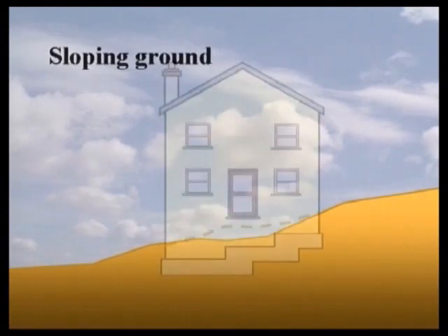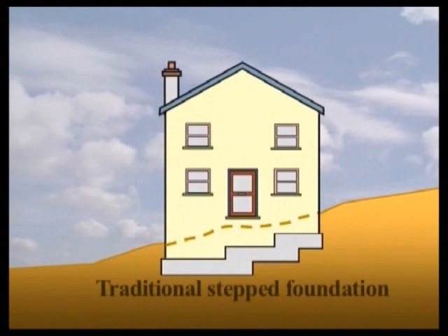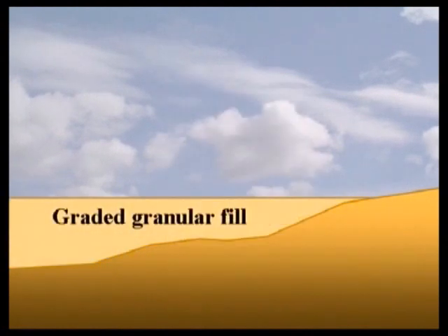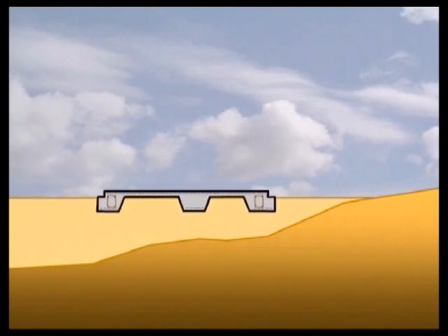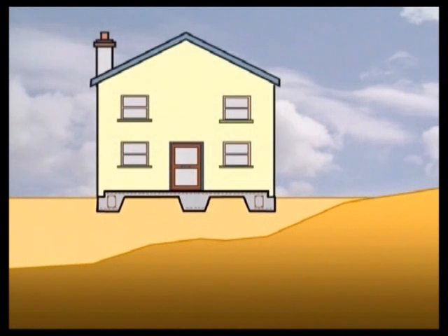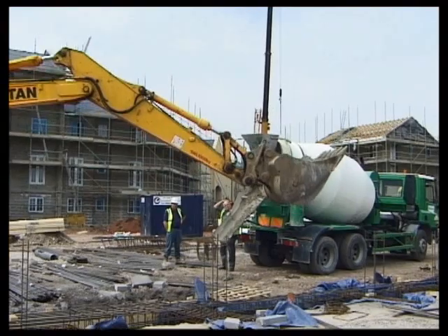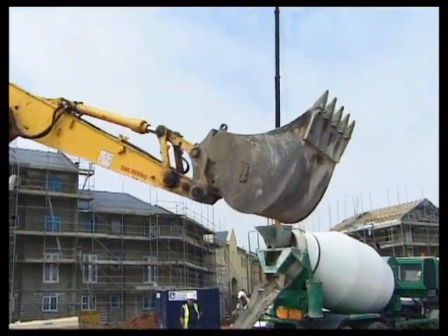Rafts have also been used successfully on sloping sites as an alternative to traditional stepped foundations. A well-compacted granular fill can form a suitable base for the raft. Raft foundations are comparatively rare. They require specialist design, and many house builders, wherever possible, prefer tried and tested strip foundations.